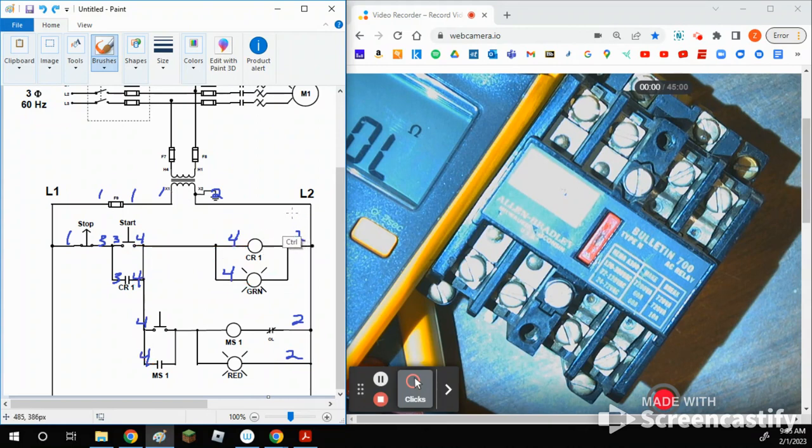The other thing that I've seen so far is that sometimes we're putting a wire 3 and a 4 together. Would you ever have 2 wire numbers on the same terminal? Nope, never. That makes the other side of this a 5. Five, 5, and 5.